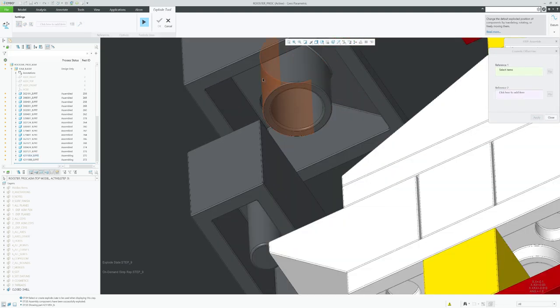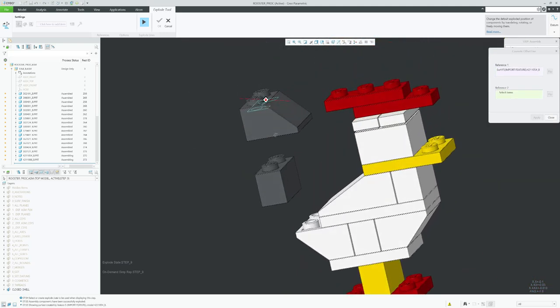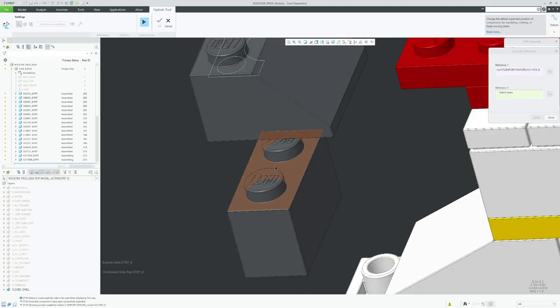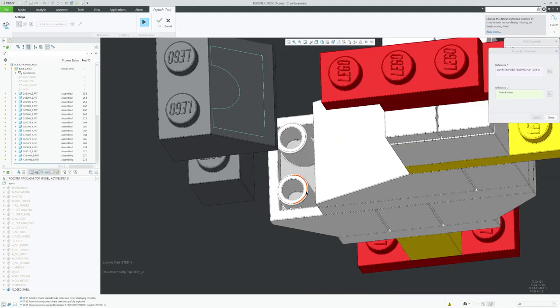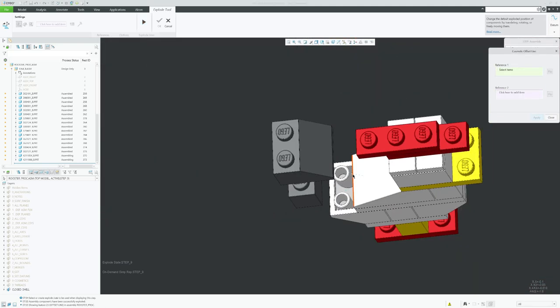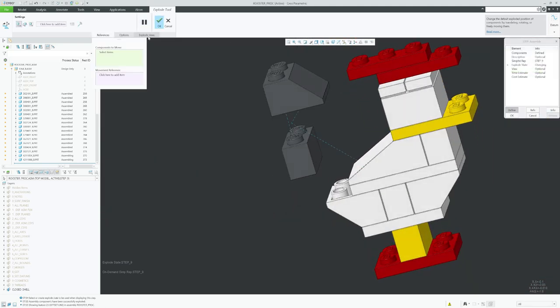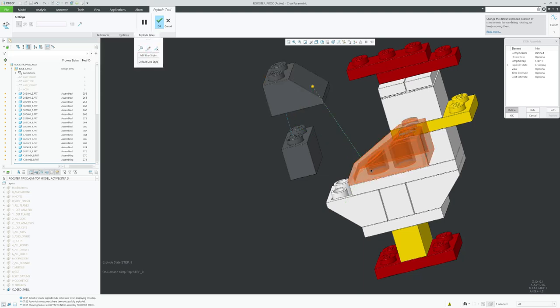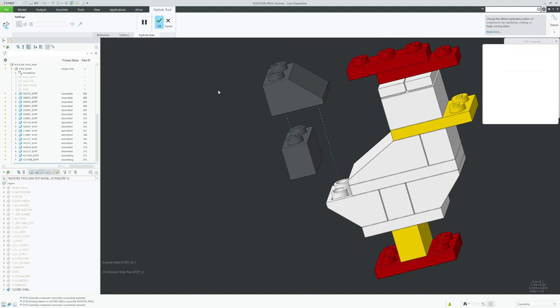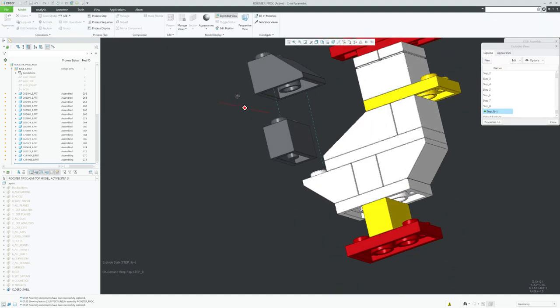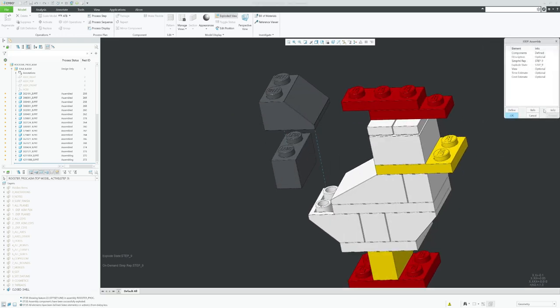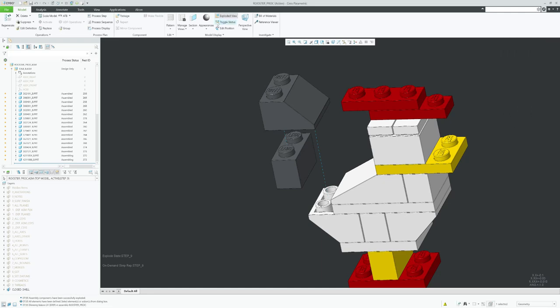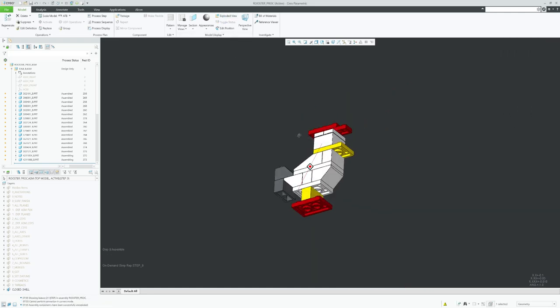Edit position. Let's move these components up. ID 1, I will select this surface. And this surface will be attached to this surface. Apply. Close. I will select this crazy line, explode lines. Then I move this here and this here. Click OK. So that tells me that this part goes there. Right mouse button, save, OK, and close. And click OK. So just click in explode view to connect everything together.